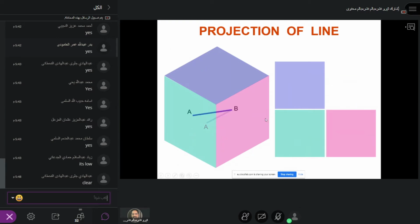Projection line. Now, if the projection line AB is slightly with an inclination, what you will see is a straight line here, which is not actual, it is a distorted line AB. You can see AF, BF on the front view, but the true size is AR, BR. This is also a tilted one, and in the top you could see AT, BT.